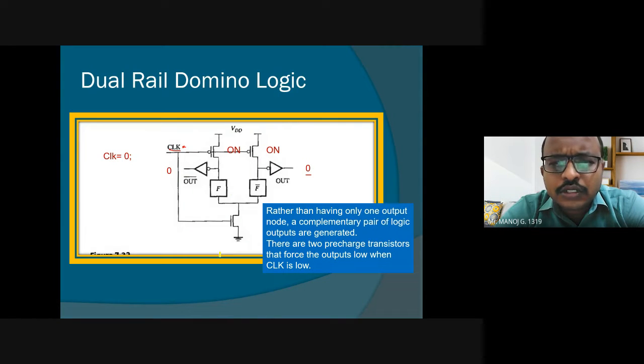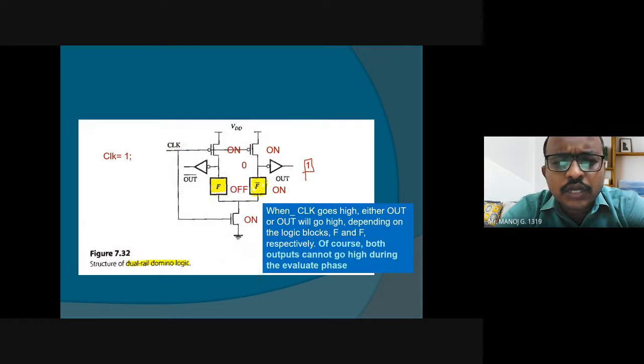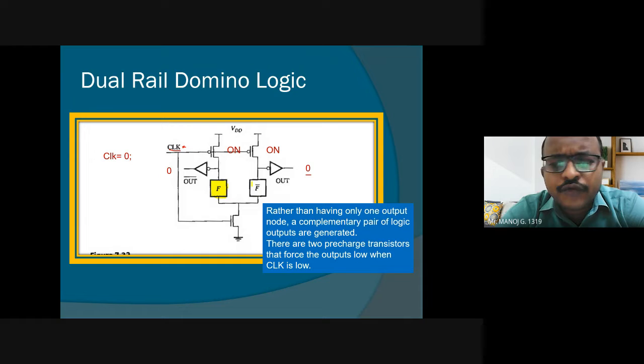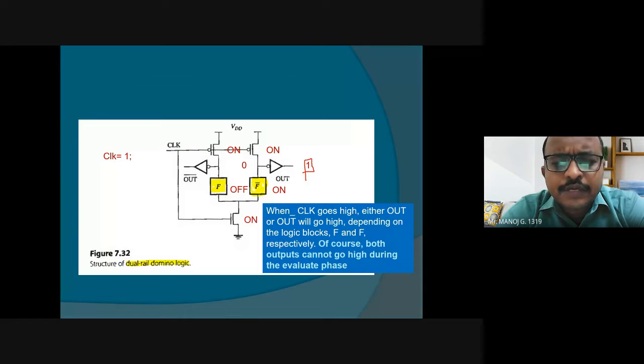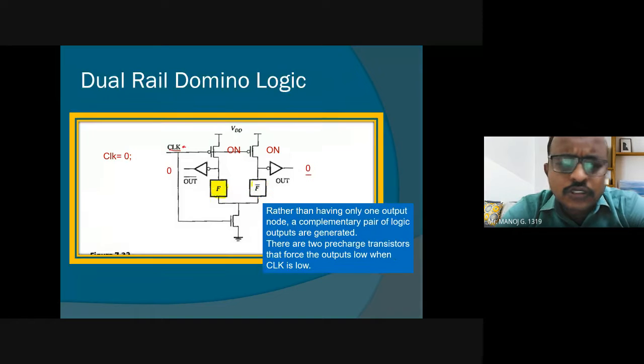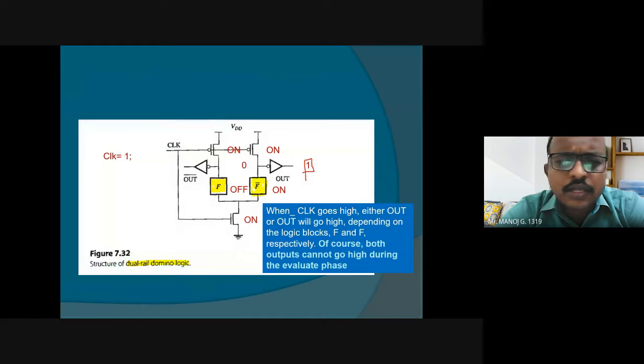They use this particular functional implementation, or the differential dual rail system, to overcome the domino logic limitation. They work in two phases, evaluation and pre-charge, where they try to get the output. When the clock is zero, you don't have much issue there.